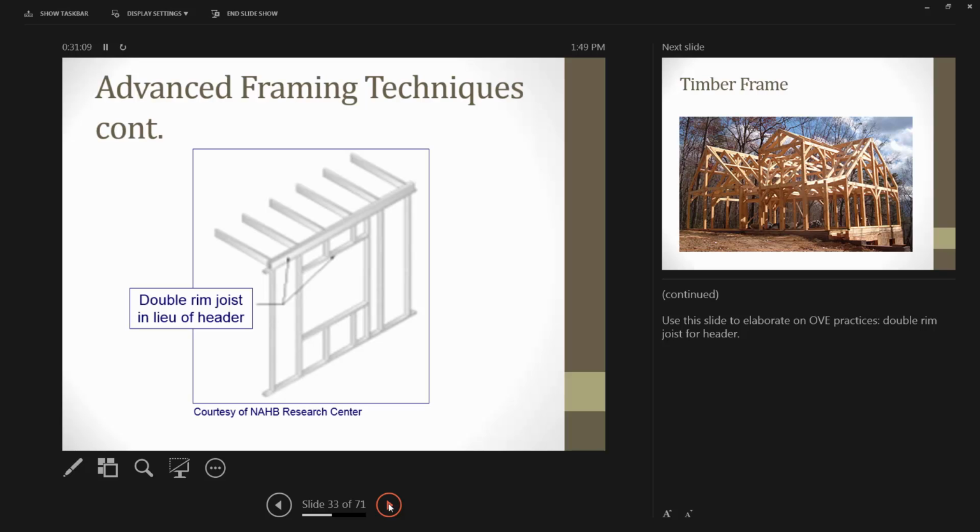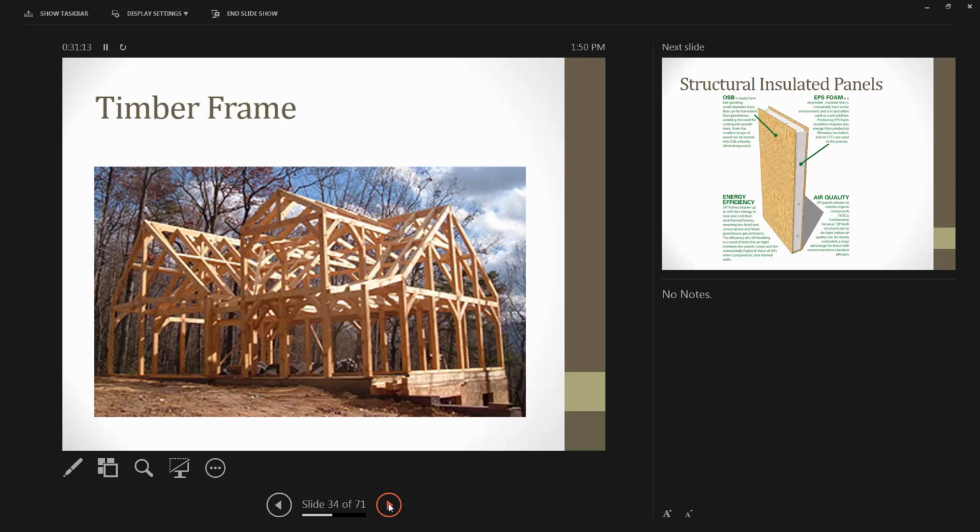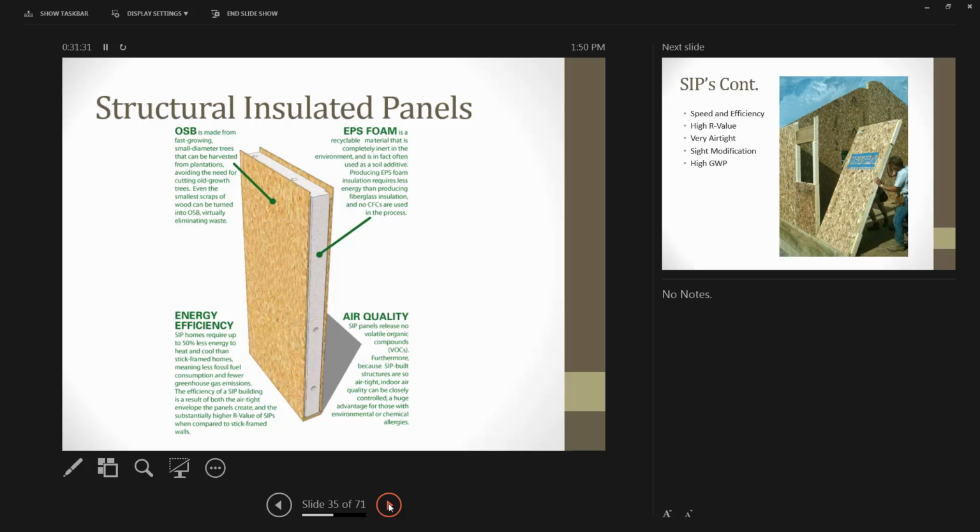Yeah. So a couple more. Another wood framing is basic timber frame. Old school barn raising, but you're seeing it more and more with the advent of different types of skins that can be used. This is usually just an internal skeleton, and then it's wrapped completely. The one that we're seeing more and more of now in wall assembly systems, especially for residential, is structurally insulated panels,